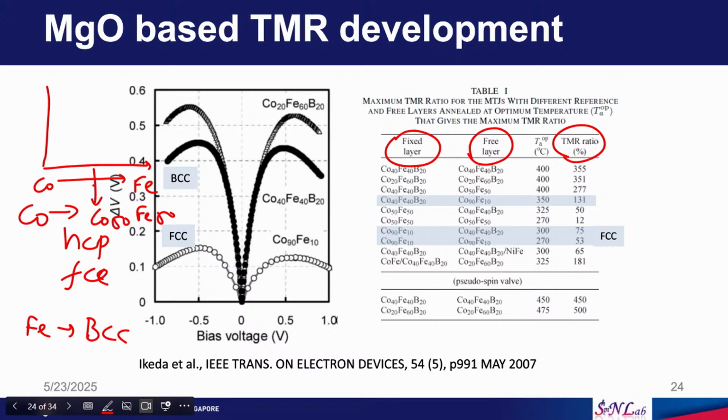Okay, so, depending on the relative composition, there will be some region where the iron is lower, let us say cobalt is 85, iron is only 15. Until this region, this will be FCC, and beyond this region we will have BCC. So, depending on the ratio of cobalt and iron, you may end up having BCC structure or FCC structure.